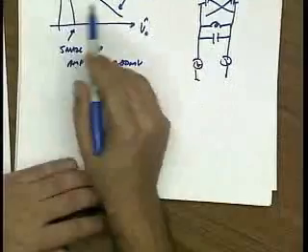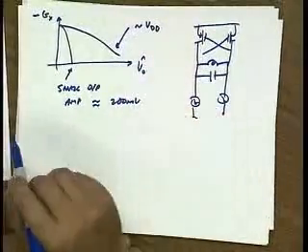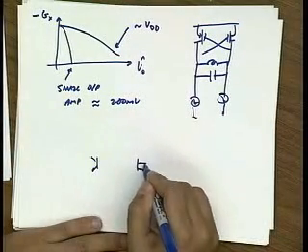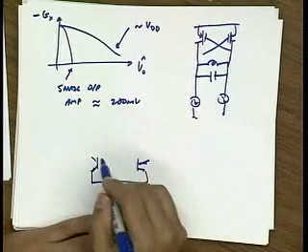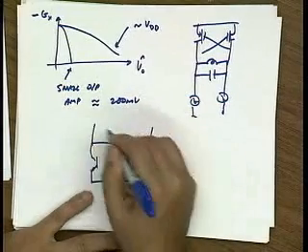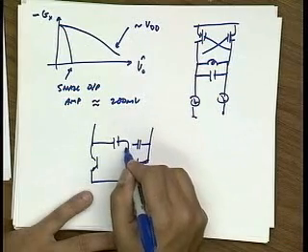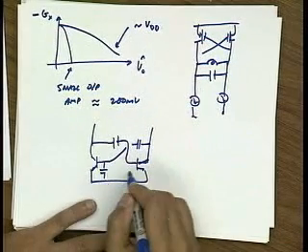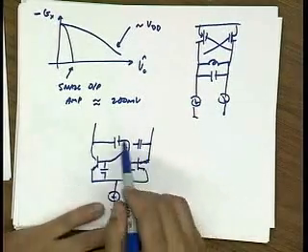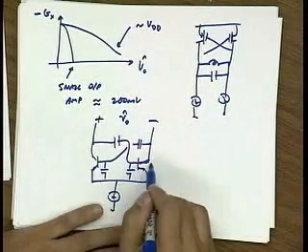If I use bipolar, the way to get larger swings, and as I mentioned earlier, swing is important for phase noise, what I do is instead of applying a direct feedback, I use a cap divider. So let me draw this a little bit better here. And there's also some intrinsic cap here. If not, you can add some. And now the voltage swing here, the large swing here, can be much larger than the internal swing.